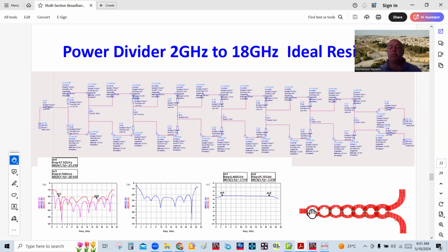The quarter wave lines become very small. You can see the impedance is varying from high to low, near 50, and how wide the 50 ohm becomes compared to the size of these rings. So one thing you might do is resort to using multiples of quarter wave lines, because the frequency response is essentially the same whether you use 90 degrees or 3 times 90 degrees. Okay, it's the same thing.